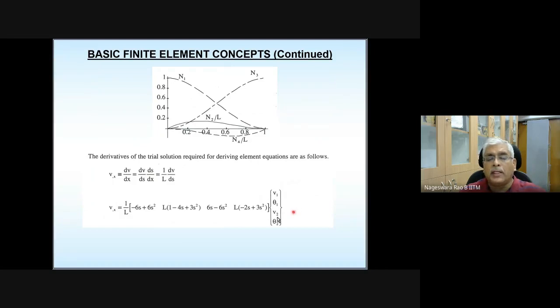Please keep in mind, these expressions for the finite element shape functions and their derivatives are valid only for that mapping. Here we mapped onto a parent domain going from 0 to 1. Instead, if you decide to go with a domain going from -1 to 1, then you need to rederive all this.